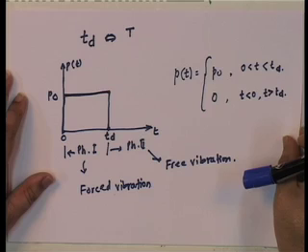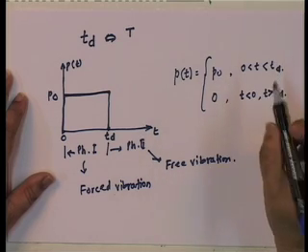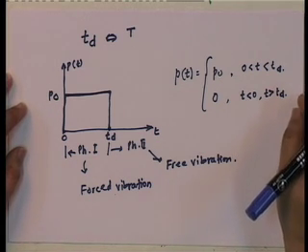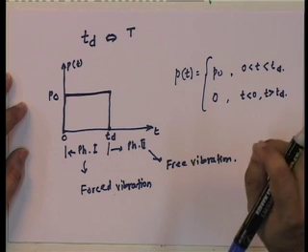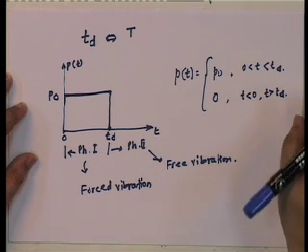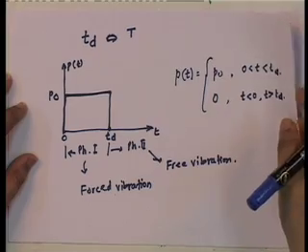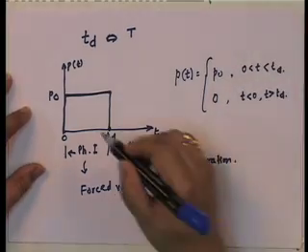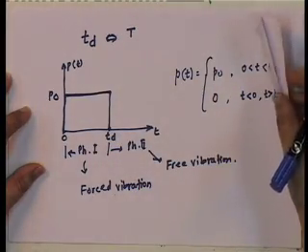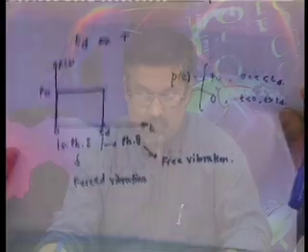Interestingly, as we saw when looking at damping, in free vibration damping takes some time to start off. Viscous damping takes off only after 1 or 2 cycles of vibration. Since T d is of the same order as T, you are not going to get 2 cycles of vibration at all.